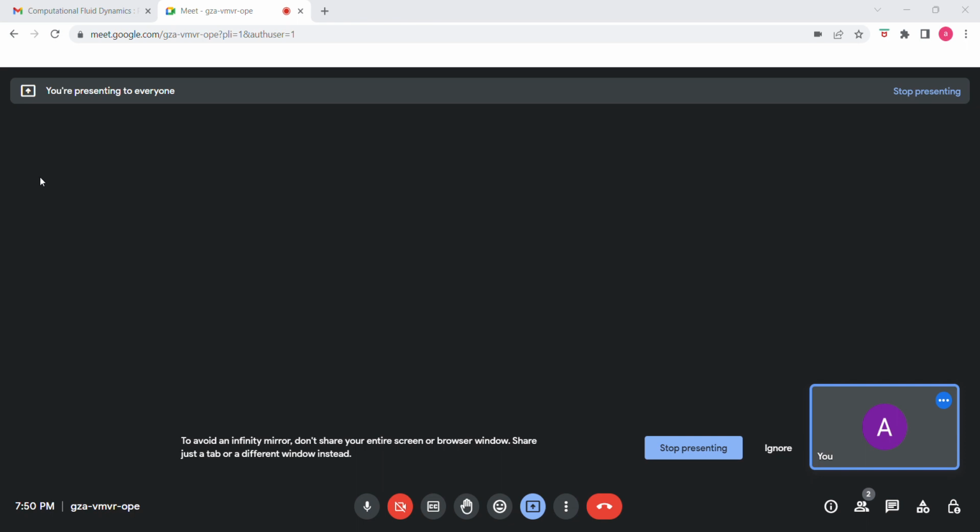One last time we'll go through the problems. The first question was this one-dimensional problem, q is equal to k d square T by dx square. Based on this problem, we found out the units for q by using a dimensionally consistent approach, and based on this we also found out what boundary conditions should be used to get the values. The thing to be remembered here is that we need values at both the ends, or value at one end and the flux at the other end.